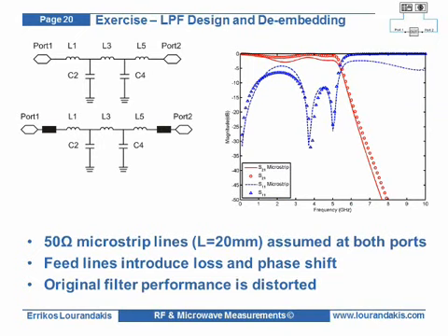Starting with the PCB layout, we can proceed with the simulation of the low-pass filter. Inserting the models for the SMD capacitors and inductors into the PCB model and performing an electromagnetic co-simulation will result in the S parameters of the PCB low-pass filter. Using only the SMD models without the microstrip lines will result in the original filter S parameters.